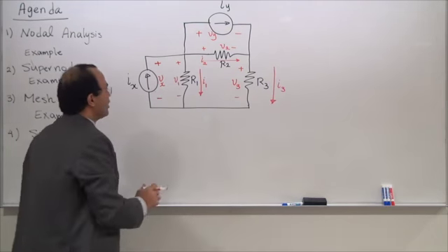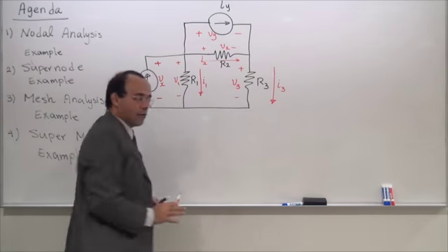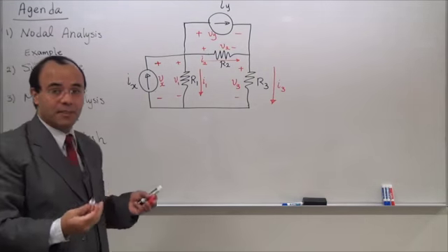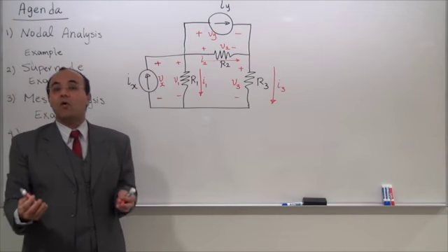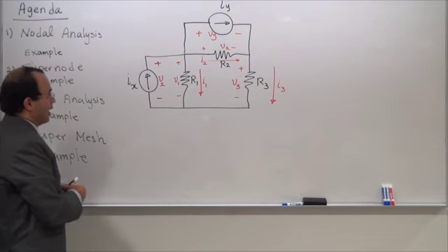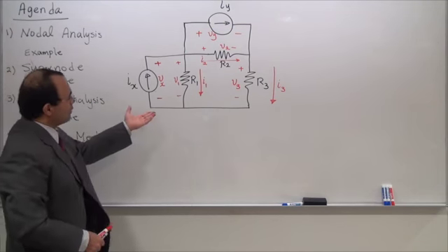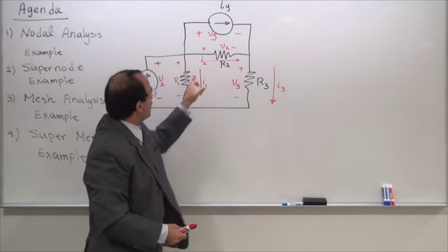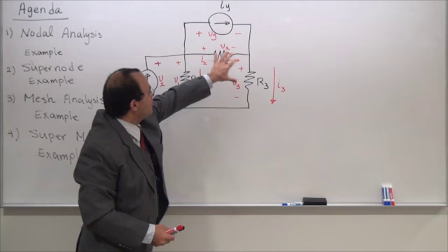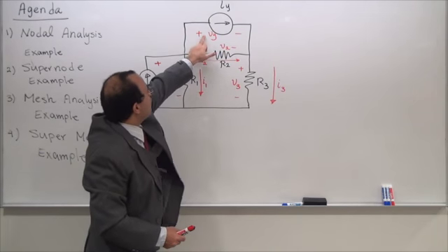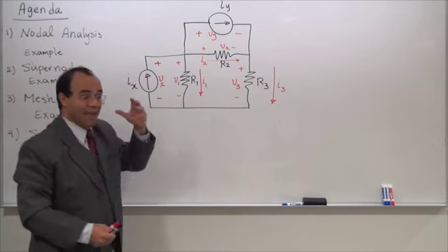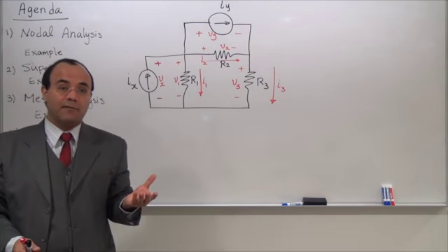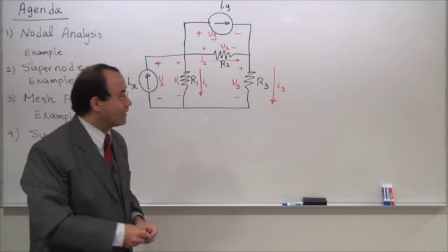If you are free initially, you can obviously assign the voltages anyhow you like, but then the currents of resistors are not yours. The same thing is true. There is some freedom initially, but eventually you are locked into the Ohm law, and you have to follow that in order to be safe. So let's take a look at this system. How many unknowns do you have? For every resistor, you're going to have two unknowns. So you have 6 unknowns already. You have one unknown for this voltage, one unknown on this, you have 8 unknowns. If I go by chapter 2, I would really need to have 8 equations, 8 unknowns. Let's see if we can get that far.